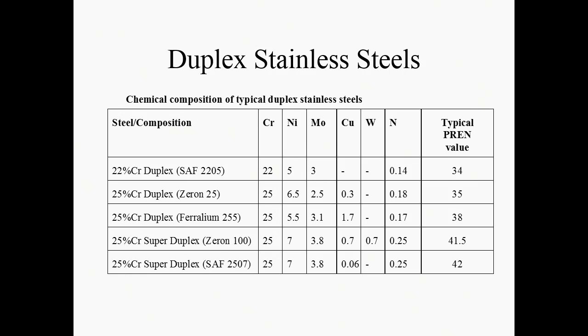Now, what I would say is as you go from duplex to super duplex, the alloying element content goes up. So, what I've been saying, higher cost. Everything comes down to cost in these cases. Going from a duplex to a super duplex might add, on a long pipe run, £100,000 onto the price of your job. So you've got to want that. You've got to be able to recover that extra price. Duplex might be okay. You might even say, well, we'll have a clad pipe or something which is cheaper to make. You have to be careful.